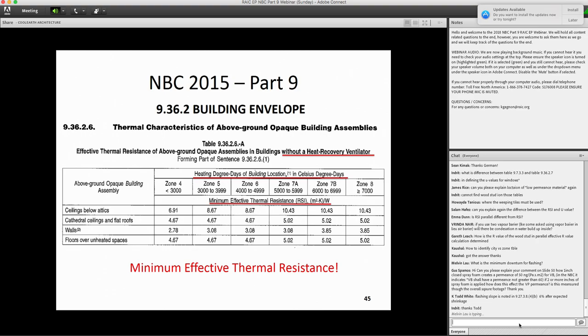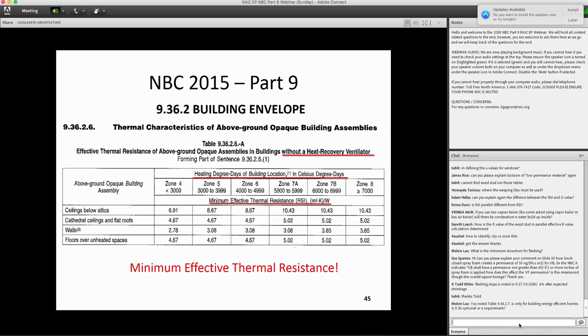It's a duct that you have below grade surrounding the perimeter of the foundation. What I've been reading is that the code requires you only to have gravel, but if you have excess water or a water table nearby, you actually want a weeping tile that will collect that water and send it to the sump pump if necessary.